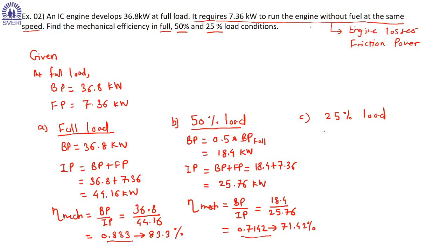In this case, brake power is 25% or 0.25 of brake power at full load condition. So this will be equal to 9.2 kilowatt.